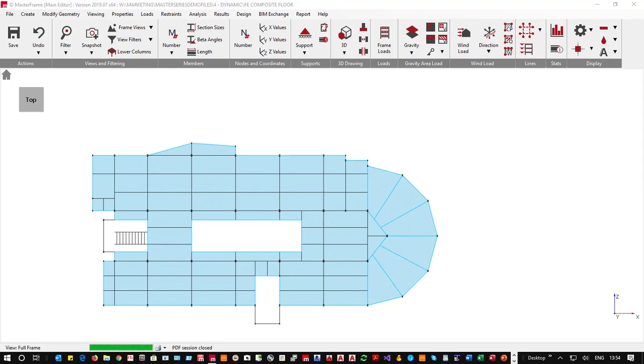Why would you need to undertake this analysis if composite beams are designed for vibration during design? Well, yeah, that's just using the very old-fashioned square root deflection over 18 calculation to get a natural frequency of a single beam. We're looking at whole systems here, and we're looking at not just the natural frequency of the whole system, but the effect of something happening in one area to another.